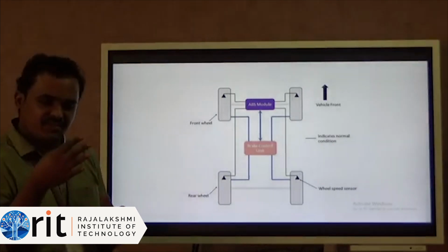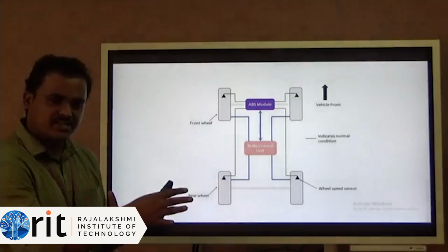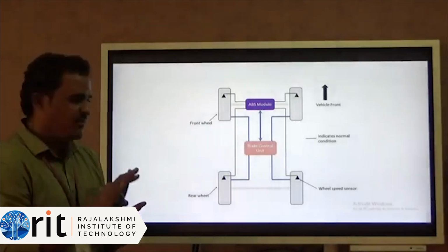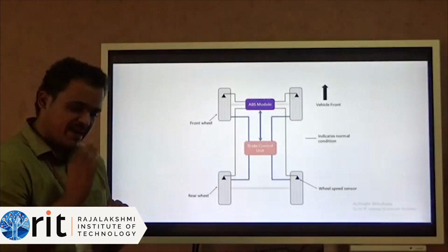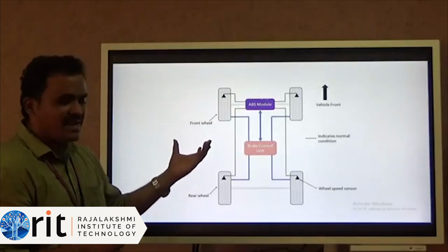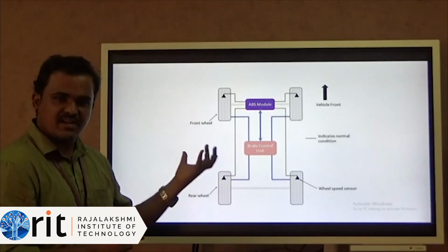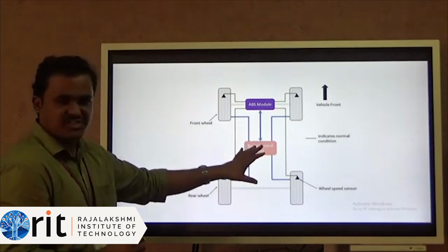The braking system will act. First it will press, then release, then press, then release. Even if you are applying the brake continuously, if the pedal is pressed continuously also, the brake pressure will be relieved, pressed and relieved, pressed. This kind of pulsation will be happening.